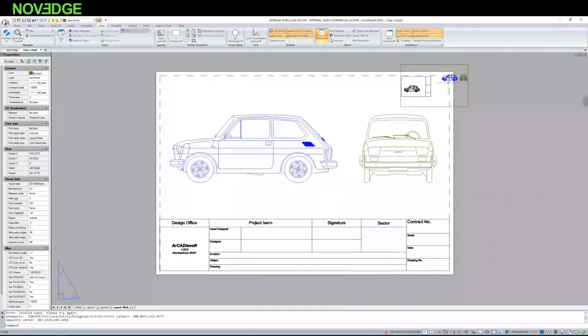And again, please note that the whole drawing is displayed just like before. I deliberately took out the sheet because this sheet has not been locked or turned off. And if I wanted to select that viewport, they would overlap, and it would be a bit difficult. The program might not select exactly what I want. So, as additional information, after selecting the viewport, we can lock or turn it off on the View tab in